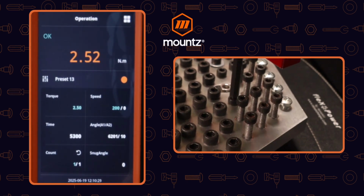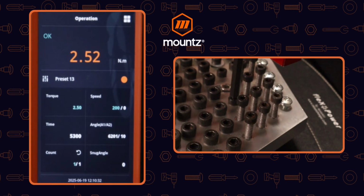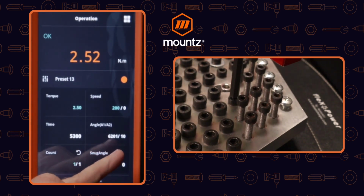So that's nearly 5.5 seconds for us to run this fastener down at about 6,300 degrees of rotation at our RPM speed of 200, which again gives us the correct clamp force and torque that we need for this fastener.